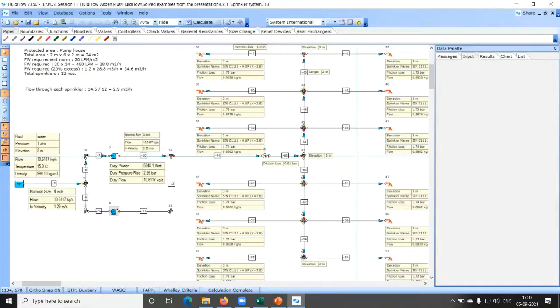But we need to create it as one of the scenarios. Then we can have the surge vessel or surge accumulator at different locations, and again we run it. That's what we do. And then the conclusion: finally, what exactly you recommend? If you have prepared any surge analysis report, I can check it. But unfortunately, I cannot share my client's files with anyone.